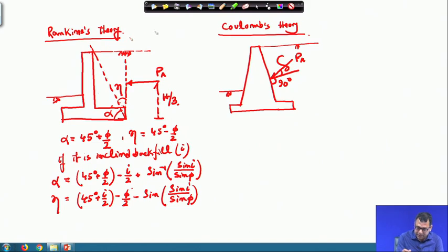If it is inclined, say suppose if your backfill is inclined, then this force will also be inclined. Okay. But even if here it is inclined, still it will act with an angle of delta. So, both the cases with an angle of delta with the normal to the wall. So, both the cases it will act in the similar condition, but here the direction will change.